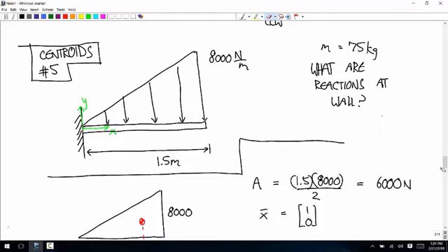Yeah. The way it is right here is more likely to break this connection than if that was flipped the other way. The reason has to do with the centroid. The area of that shape would be the same either way, but this way the centroid is over here. If that triangle was flipped the other direction, the centroid would be over here. That means in the other configuration, the moment arm would be less, and there'd be less of a couple required by the wall.